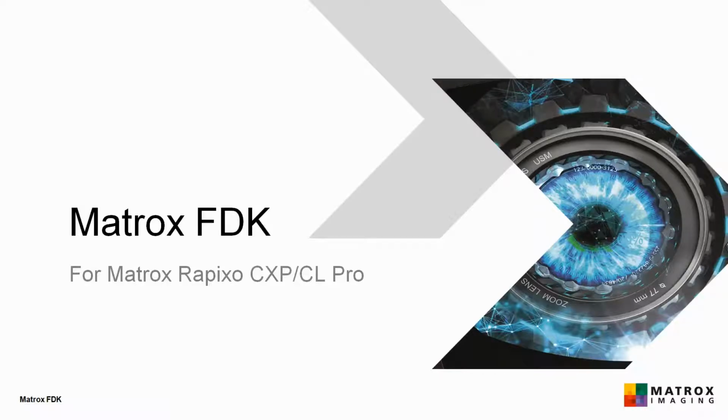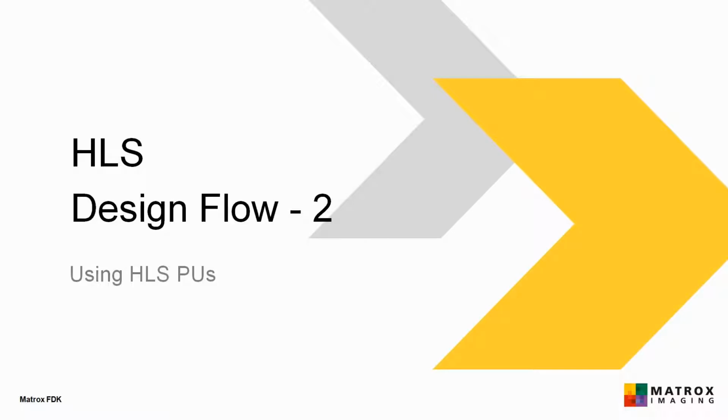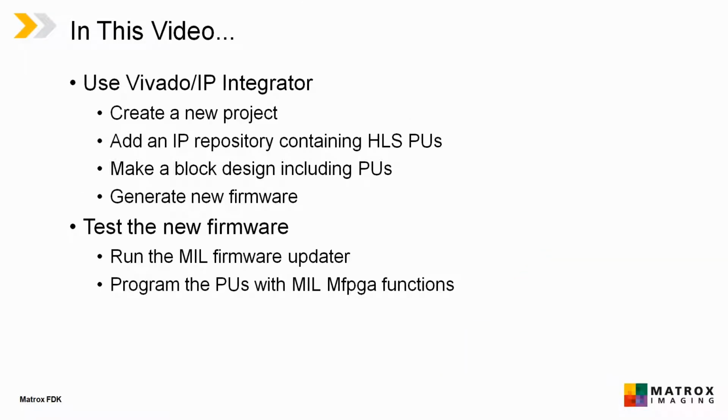This video on the Matrox Rapixo FPGA development kit is part 2 of a series on the Vivado HLS design flow. We will create a new Vivado project and then add an IP repository to store the example processing units that we generated in part 1. Next, we will make a block design that includes the example PUs and generate a new firmware file. Finally, we test the new firmware on a Rapixo CXP Pro board.